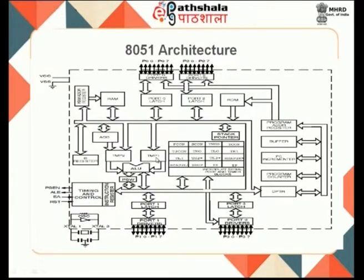So, we have two temporary registers through which all the data that has to be processed will be sent, and one of the operands always comes through the accumulator only. The accumulator is given here as ACC, and this is always available in all controller architectures, and we have a B register also. This B register also sometimes holds operands.